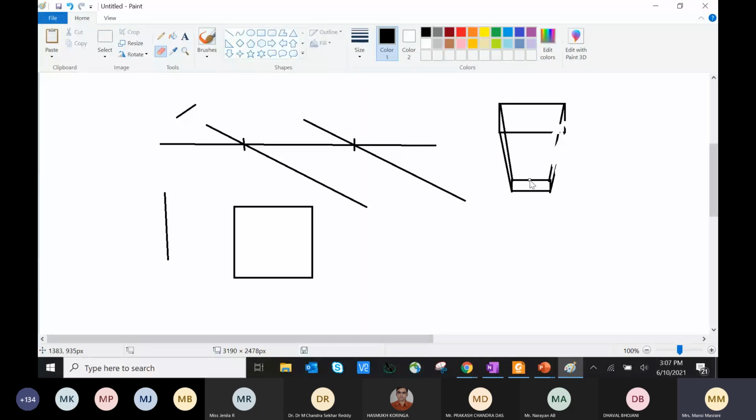So in that case, we use multiple vias at one intersection like this. This is the top structure which I'm drawing. 3 by 3, 3 by 2, whichever is preferred in your technology, whichever is preferred by your current carrying capacity. It gives multiple paths for the current distribution, and that is the reason it does not wear out easily. That is called via ladder.